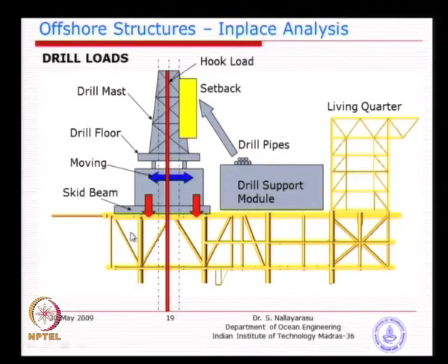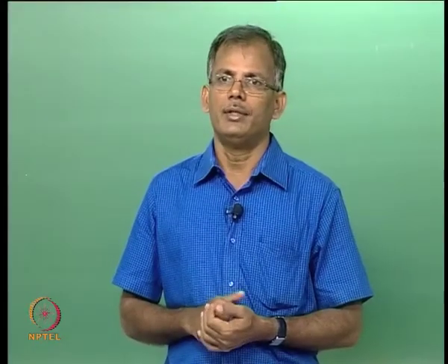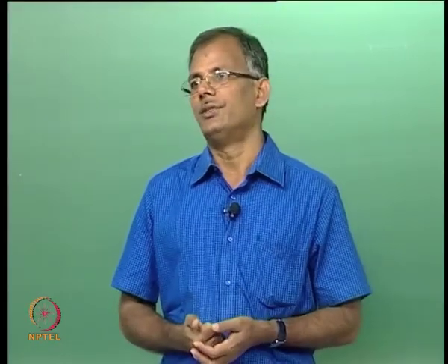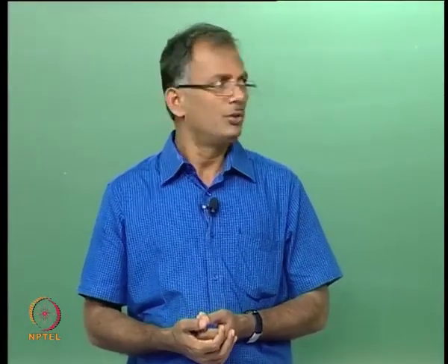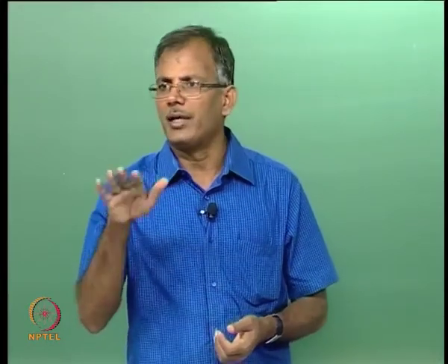They can give you the load on each of the members: shear forces, bending moments, torsional loads, all can be obtained from 3-dimensional analysis. As long as you simulate the structure in accordance with what is required, and apply the loads and support boundary conditions correctly, then you can get the loads, which nowadays nobody is doing by hand calculations.